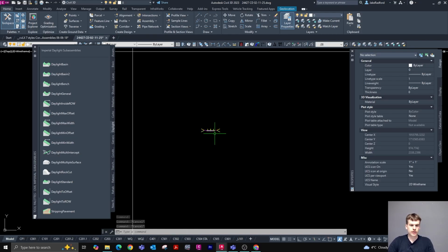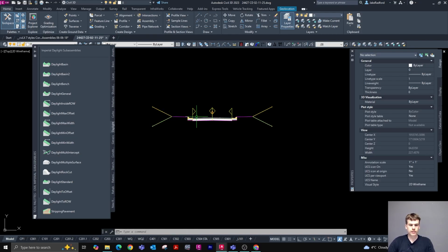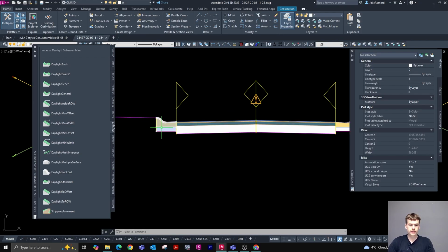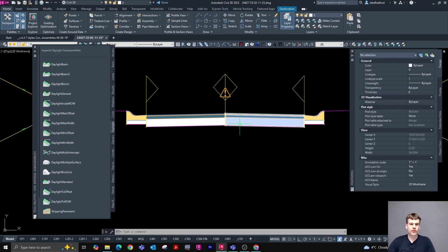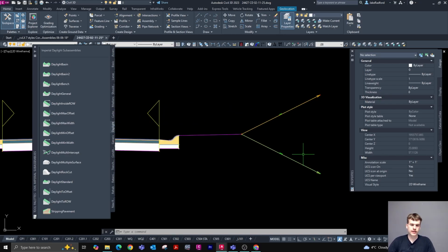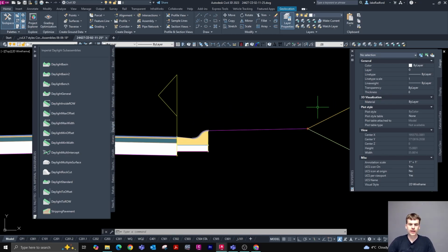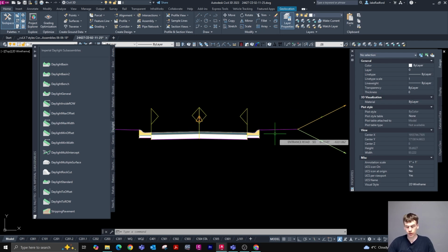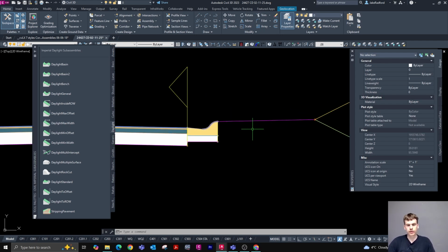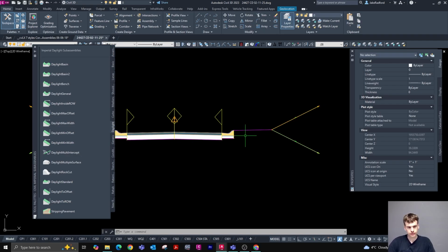So like I said, you can do a ton of different things with assemblies. If we wanted to change the curb, we can simply swap out this subassembly for a vertical curb, or for an angle curb, or for any type of different curb, or even come into our subassembly and change the width of this curb if, for whatever reason, we have to do that. Same thing with our lane widths and slopes, same thing with our daylight slopes, and same thing for this flat area provided. We could switch this out for a sidewalk if we're required to have a sidewalk at some point, and it'll grade out a sidewalk for us, etc.